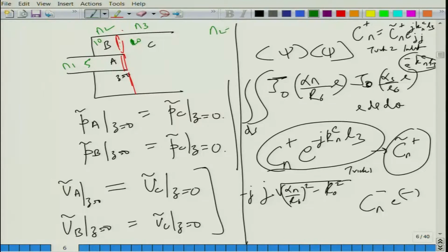Generally we consider n2 as equal to n3, that is, the number of first few modes in the annular cavity and the expansion chamber are considered the same. Inlet pipe, because those pipe diameters are typically quite small compared to the chamber, about 40-50 mm for automotive mufflers. So, we consider a limited number of modes given the operating frequency and so on.